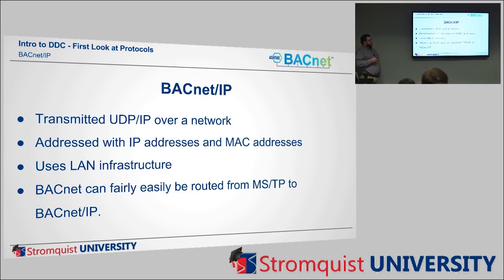Obviously you don't want to do that with mission critical type stuff where you're passing data that's running a chiller plant. But if you've got a system where if I lose communication, everything still works, that's a pretty good solution.